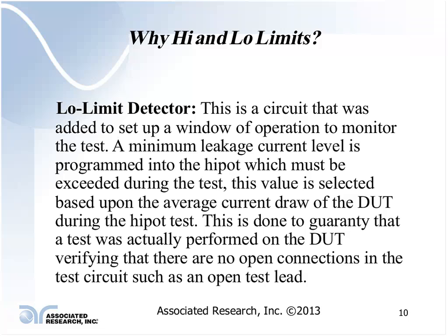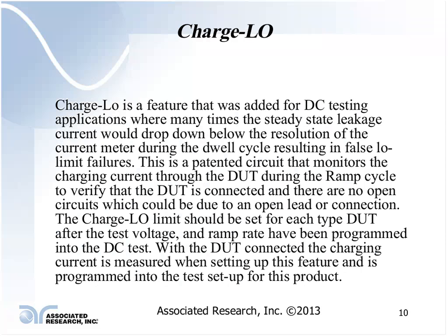One thing, it kind of tells you that your equipment is working also. If you have a low limit set and you initiate a test, if you're not drawing that low limit, it's going to set off the failure alarm. So, it's a way of going through and doing this.